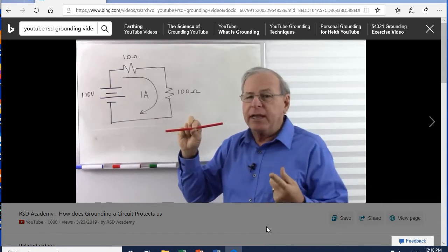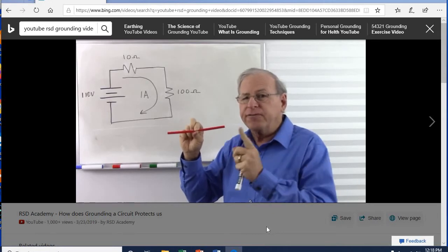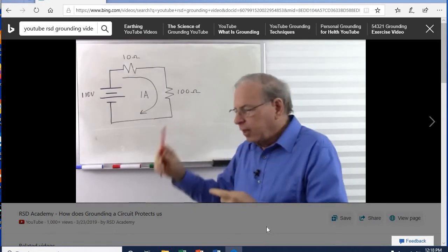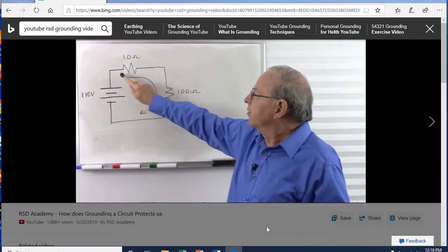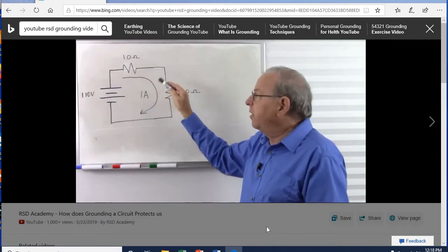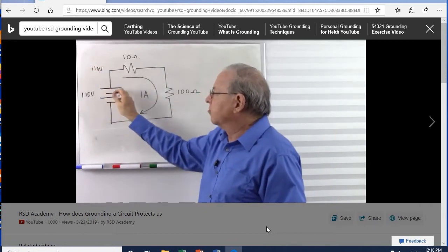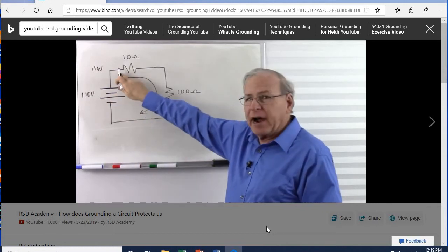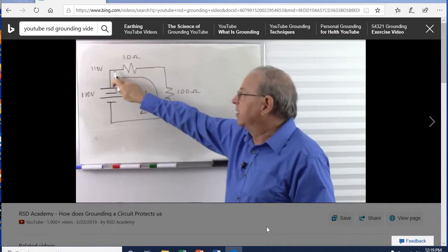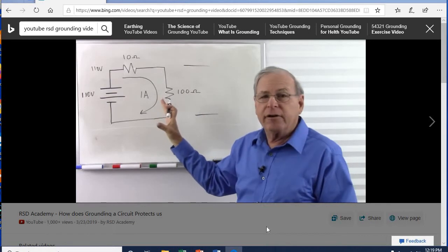And remember, any kind of pressure is always measured as a differential, and voltage is electrical pressure. So it's the difference that matters. So I have a higher pressure here and a lower pressure here. So I have the same thing over here. When I push current through a resistance, I get a higher voltage here than I do here. Now this voltage is pretty much locked in at 110 volts because it's locked into the battery voltage. So if I have a higher voltage here and a lower voltage here, I must have exactly that, higher voltage, lower voltage. So my voltage here is something lower than 110 volts.